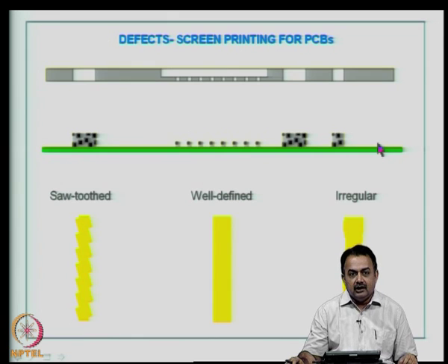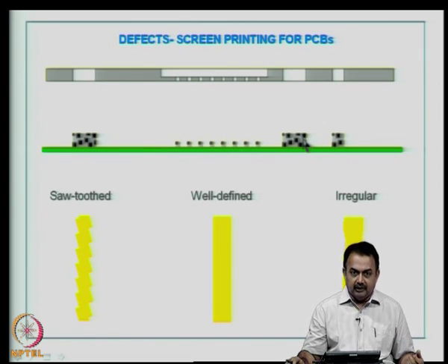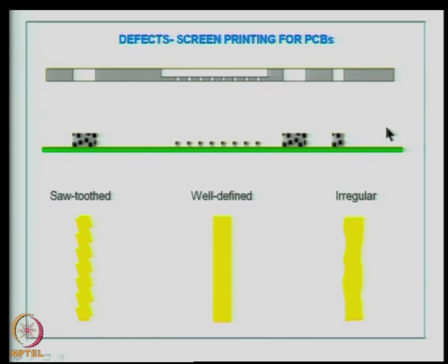Now, we can see here pictorially defects that can be observed during the screen printing process. This is the stencil, this is the PCB surface. You can see if you have the controls right in your equipment and the process steps, you can get perfect dispensing of the material. It can be an ink, it can be a solder mask, it can be a white ink for legend printing, or today screen printing is also used for solder paste dispensing during surface mount assembly. So, in this case this picture typically depicts metal particles embedded in epoxy medium, and what I have basically shown here is a screen printing process for solder paste dispensing onto the lands that have been generated already on the printed wiring board. At the bottom picture shows you typical defects.